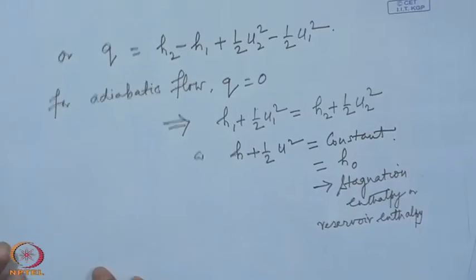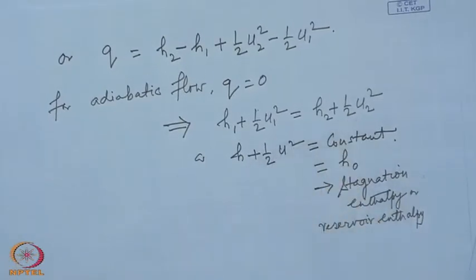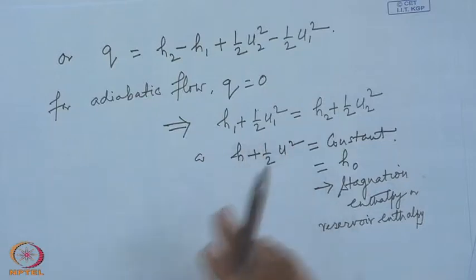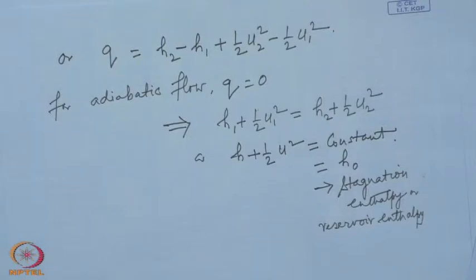This is of course the integral form of the energy equation, and as before this integral form is valid if there is some non equilibrium or non uniform region between station 1 and station 2. That is, even if there are viscous stresses or heat transfer, the equation remains valid, provided station 1 and station 2 both represent equilibrium states.